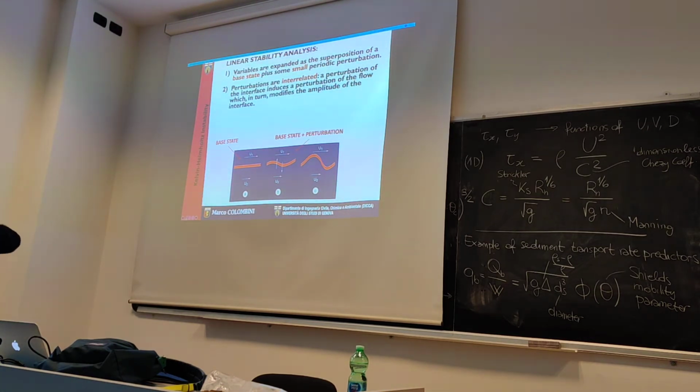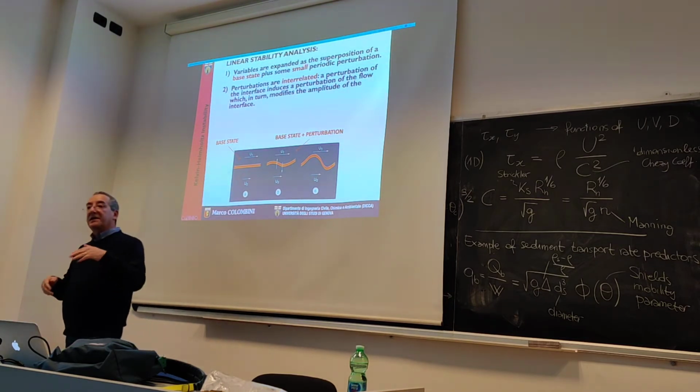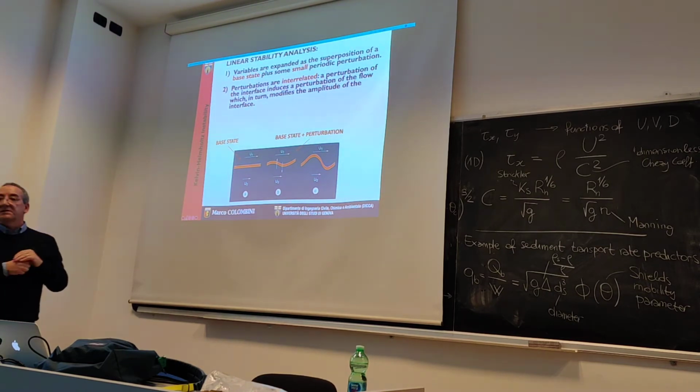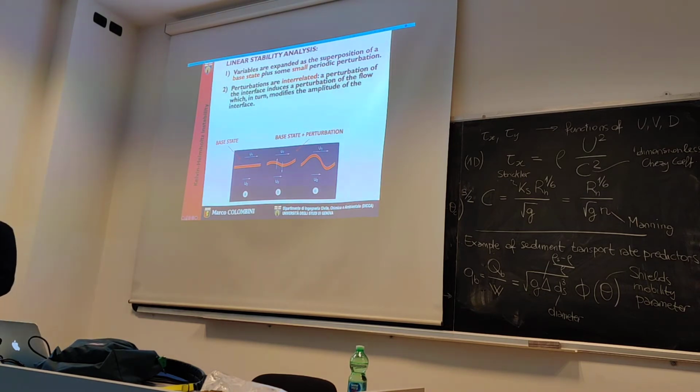There is a feedback between one perturbation and the other, so that you think of perturbing slightly, for example, the shear layer that you have seen in Kelvin-Helmholtz instability. So you have a very sharp change in velocity at the interface. If you assume that you have a little perturbation of that, then this perturbation will induce an oscillation of the interface between the two layers.